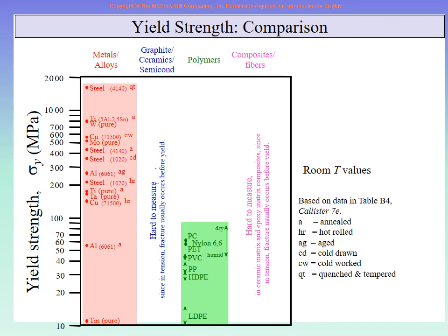Yes, you are right. Brittle simply means that there will not be plastic deformation. There will not be large plastic deformation. It will not be very ductile. So that is the problem. If it is a strong ceramic material, then the strength is high. The line on the stress strain diagram goes up and up and up, but suddenly it finishes in a straight line. It does not go into the large deformation. So if it does not go into plastic deformation, there is no yield point. The end of the elastic region is there, but you cannot call it a yield point.